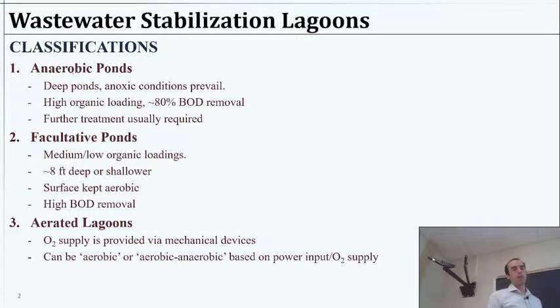Unless you cover the anaerobic ponds, you're probably going to have some amount that's aerobic on top as well, or maybe you just cover it to avoid that. But these facultative ponds, that's kind of the way they're designed, and then there's some mixing of your organics just by diffusion through these layers, and overall you have a combination of the aerobic treatment and anaerobic treatment, and you end up with a pretty good BOD removal and processing of your waste there.